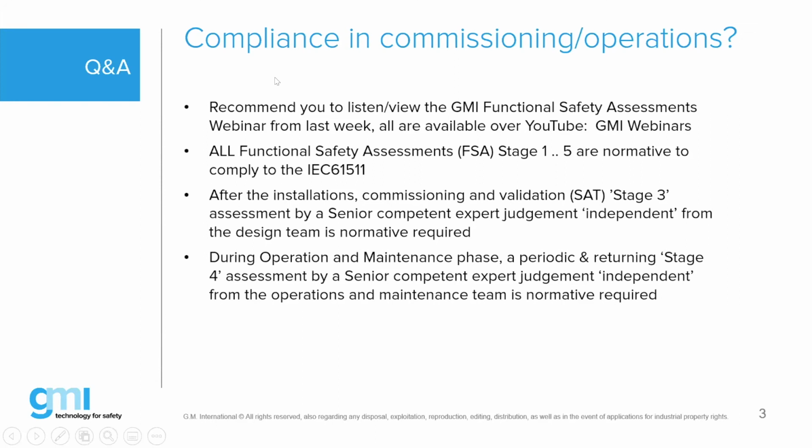So for the commissioning phase, it's clearly your stage 3 FSA, or functional safety assessment. That's expert judgment, which needs to make a judgment based on documents that during the commissioning, you actually fulfill the requirements you had to fulfill to validate the system and prove you reach the requirements from your safety requirement specification. That's the first answer.